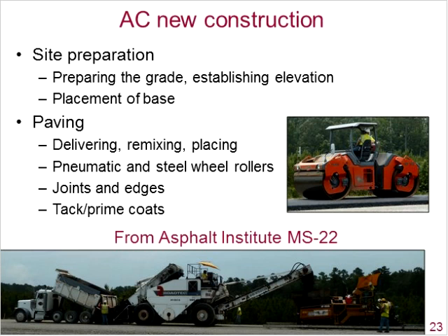And I wanted to point out here that there have been some studies where they saw a joint into the asphalt concrete pavement. And what that would do is it would force a crack to grow there, which in theory makes it easier to maintain, because if you put that crack in and immediately point the sealant in, then that crack will form at that location. But if it's already sealed, the material and the water won't get inside that crack. But asphalt concrete cracks very uniformly due to either thermal cracking or other types of cracking, and that usually provides enough stress release. You need to get out there and seal those cracks in an efficient manner, but there have been talks of using joints like the PCC pavements.